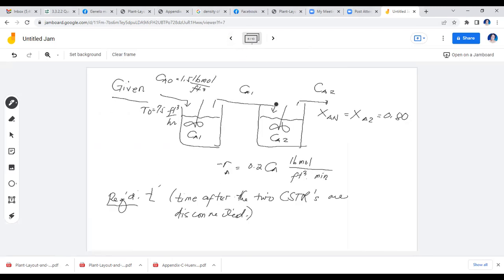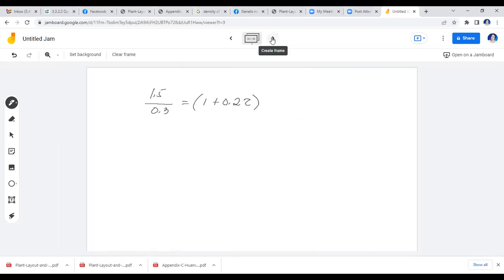And there's no way that you can determine it fully because you're only provided with the V sub O. You're not given the individual volumes of the two CSTRs. So we'll be determining now the tau based on this formula, so that would be base 2. Your tau in here, the space-time in each of the individual reactors, is 6.18 minutes.